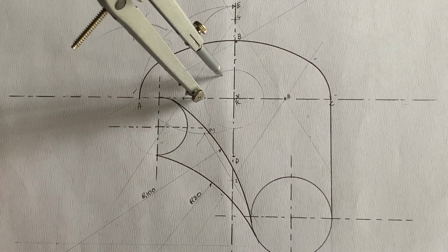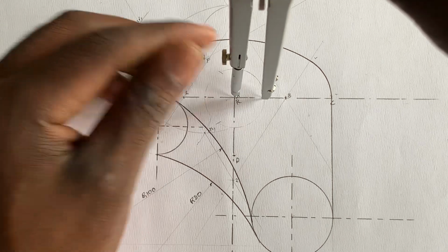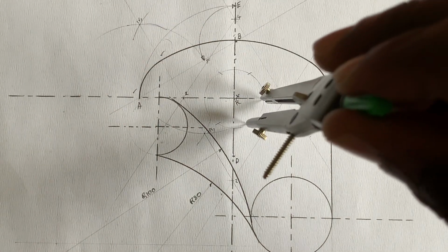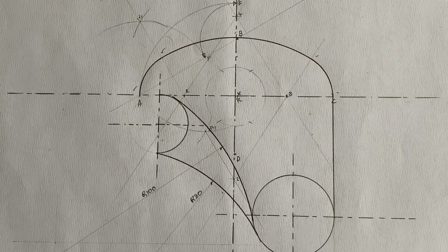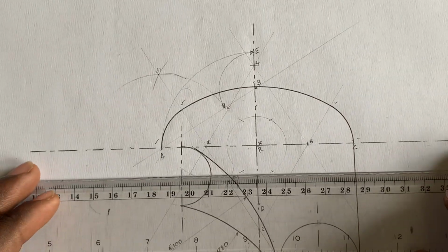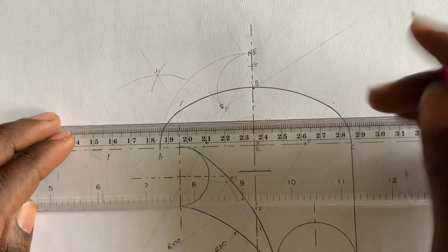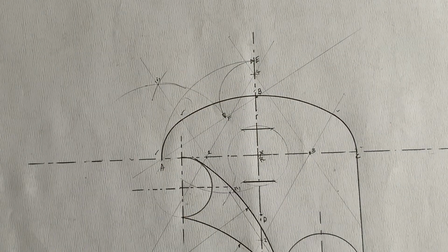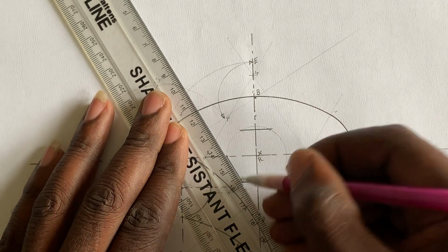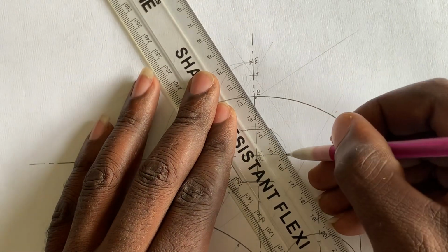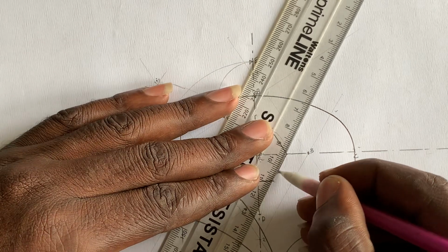Then you just strike an arc here and strike an arc there. You get it? Then you come to this other one, place it here to the center, you strike an arc here, you strike an arc there, crossing this line of yours. So now you can simply take your 30mm ruler. Before even that, these two lines must be at the same point in terms of the horizontal. Again, this one, the same straight line in terms of the horizontal. You get it? Then from there, take your 30mm, you join this one with the center, you join this one with the center, you join this one with the center.